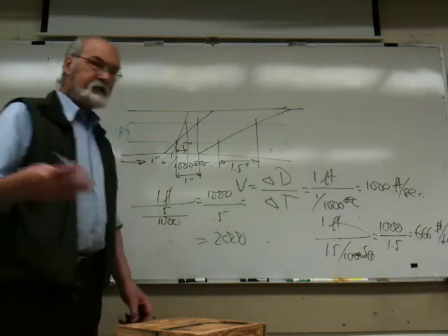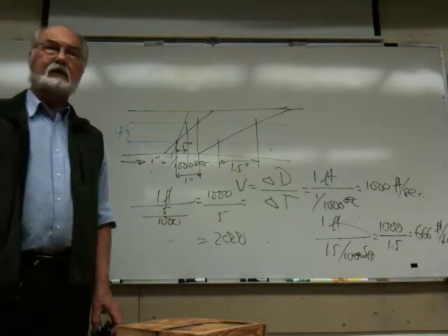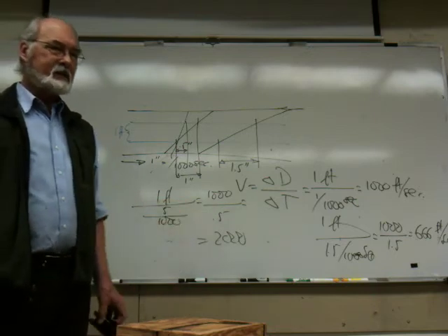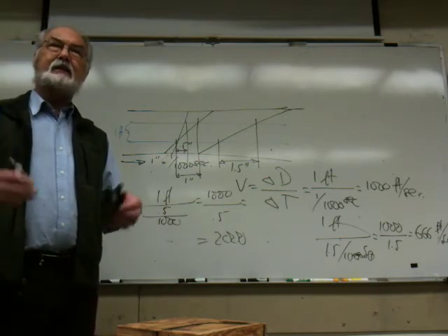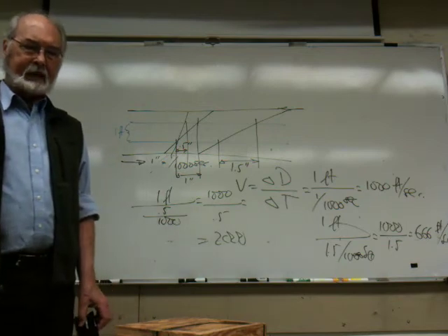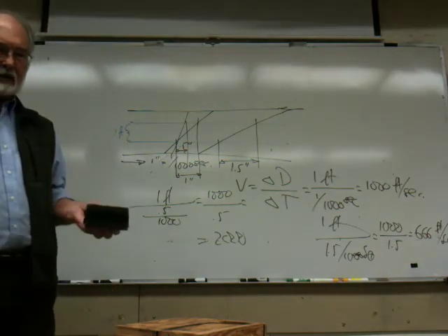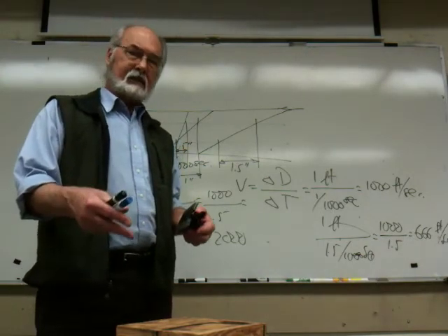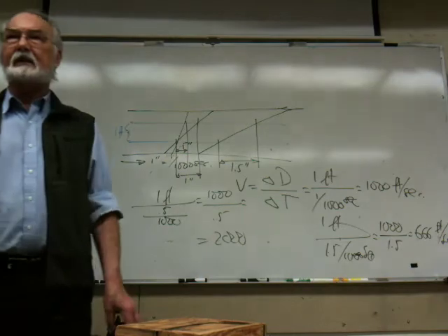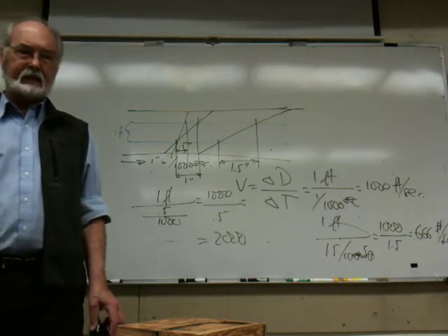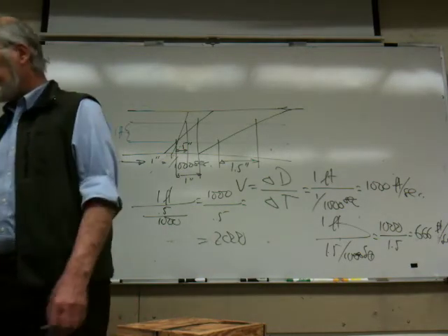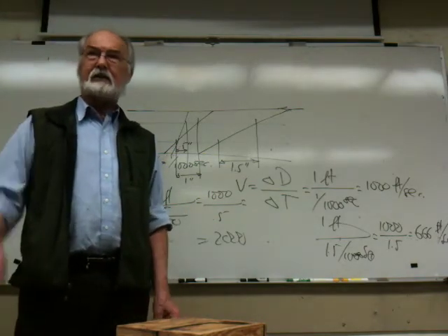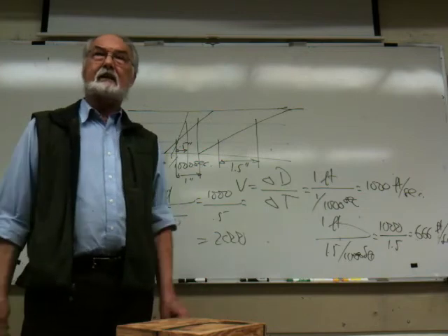One of them is to use a flashing light, a stroboscope. A calibrated stroboscope. It can't be just any stroboscope. Something that tells you that the flash is flashing at a particular rate. And then if you use the stroboscope properly, that will tell you what the RPM of a rotating object is. We'll get into that later. But it's kind of, again, as I said, a falling off a log answer. Oh, use a stroboscope. Car people use it all the time, don't they?